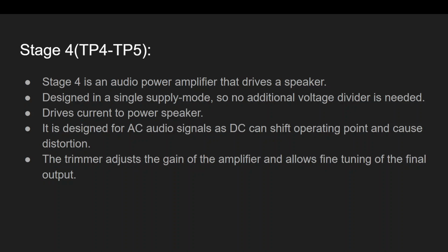Now, for stage 4. Stage 4 is an audio power amplifier that drives a speaker and is designed in a single supply mode, so no additional voltage divider is needed. Stage 4 drives current to power the speaker and is designed for AC audio signals as DC can shift the operating point and cause distortion. Stage 4 also has a trimmer to adjust the gain of the amplifier and allows fine-tuning of the final output.